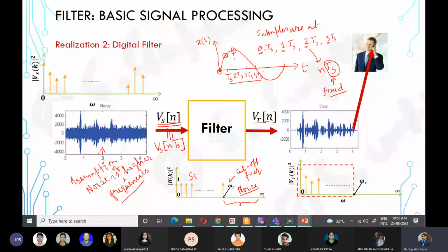If I can remove that higher frequency component, that is, if we can design a filter with this kind of response, where we have a certain cutoff frequency Wc, and within this band all the signals pass with their original amplitude, but beyond this band the signal amplitudes are attenuated ideally to 0, then we get the signal component x(n), with the noise removed. And so we get a clean signal, right?